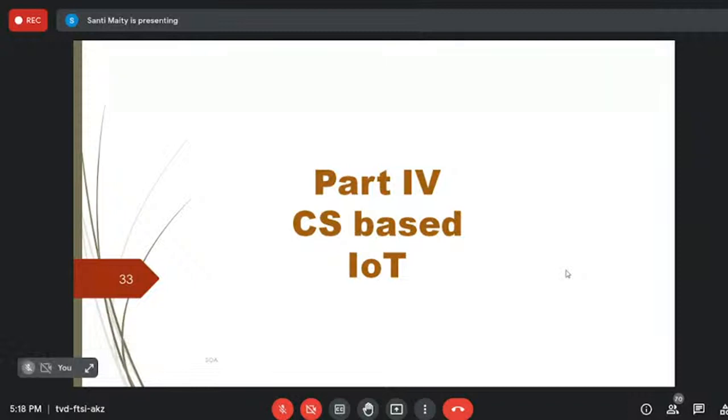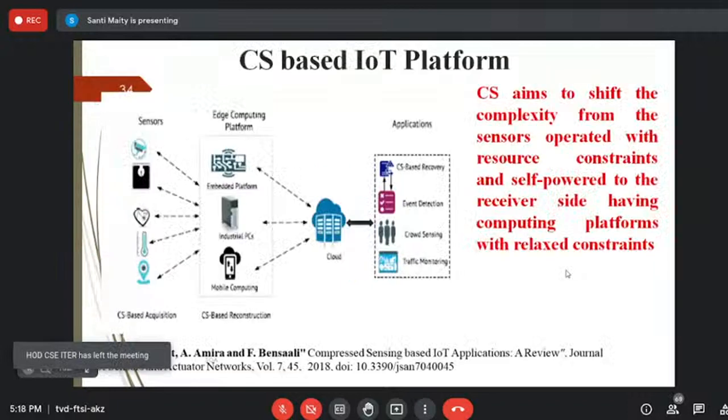When we do the Fourier transformation, the basis function is fixed, e to the power minus j omega. When we choose the DCT, discrete cosine transformation, the basis function is fixed. Even for DWT, the basis function is fixed. Now, what can be done? Which representation space will my data at hand be partially represented in? It's again an issue of dictionary learning, and people are working on it. But it is true that whatever data the IoT sensor captures can be partially represented.